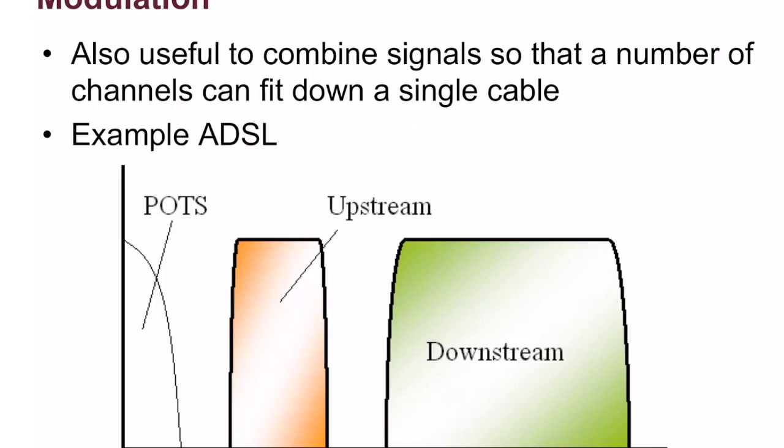So the ADSL, the broadband that brings cables to your home, has translated some of the data that is sent onto different frequency bands. So what you have is, down at the lowest frequencies, we have the telephony system, plain old telephony, POTS. Whereas the data you're transmitting is in a frequency band here, and the data you're receiving is in a frequency band above it.